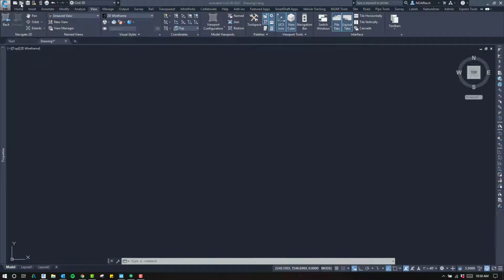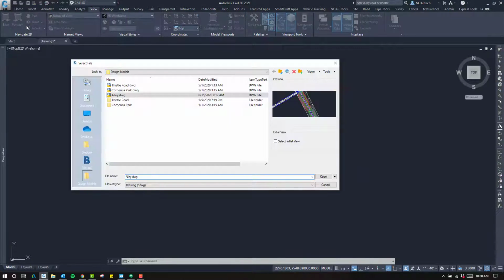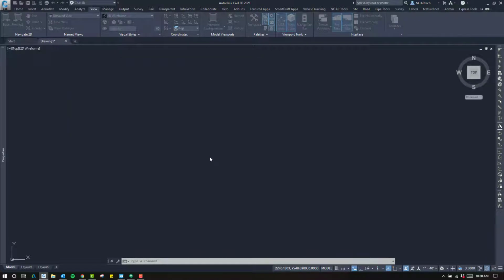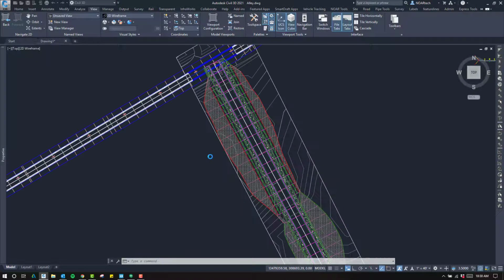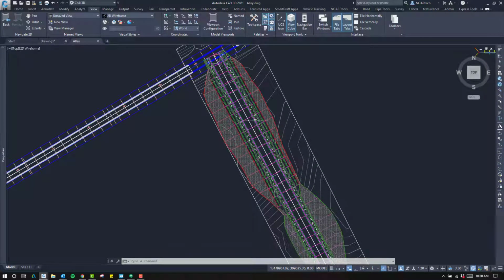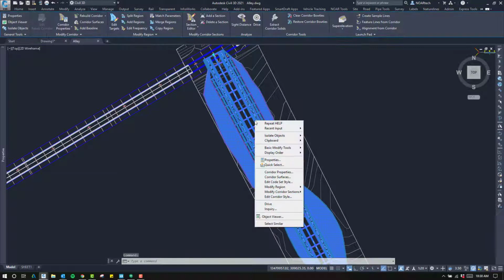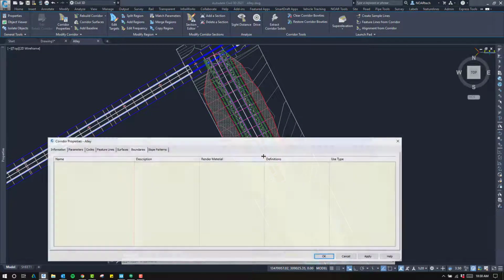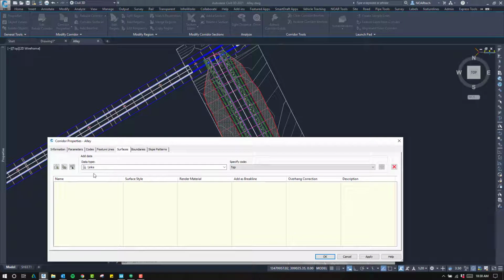So once he starts out, the first thing he's going to do is go into the BIM and open up his model. Now this is the same model that I've worked on, that Tyler's worked on. We're just taking it over from Tyler's point now, where he's already created our corridor with our grading. So the first thing that Chad's going to want to do to be able to have the pipe network flow correctly is to go ahead and create a surface for the corridor.